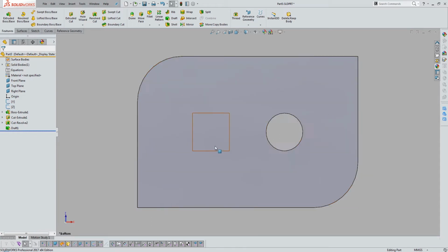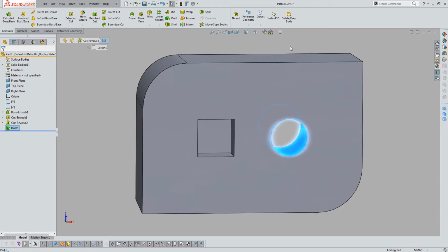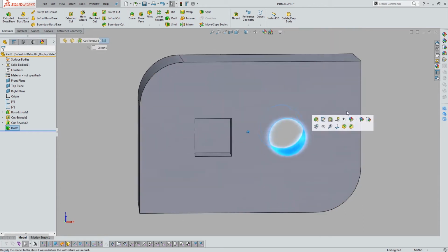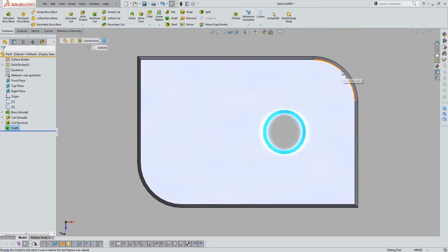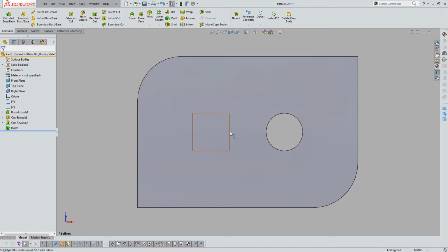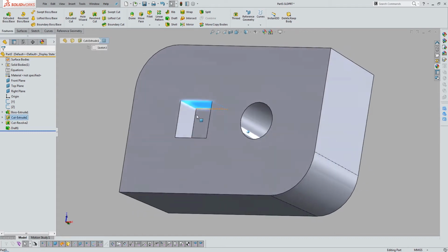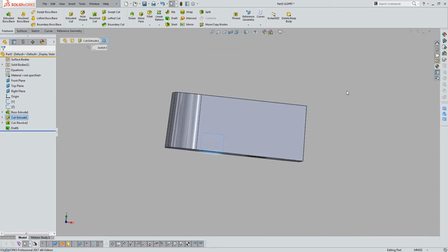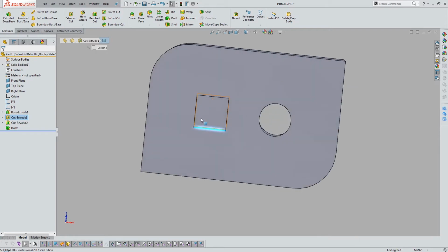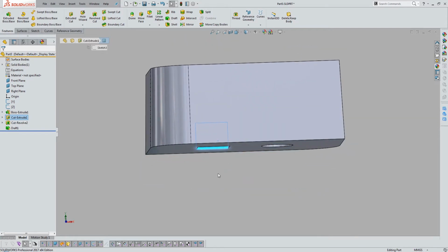Now it's upside down. And it looks like I can't see any of these outside edges, and I can't see these edges, or rather these sides. Can't see those from the bottom, but that's okay because I can see them from the top, which means that I can pull them off of this side. They're going to be on the top tool. But on the bottom tool, the bottom half of our mold, I'm going to need to create this feature because I sure can't create stuff down here with a mold that's up on top. So this is going to have to pull down off of the bottom.